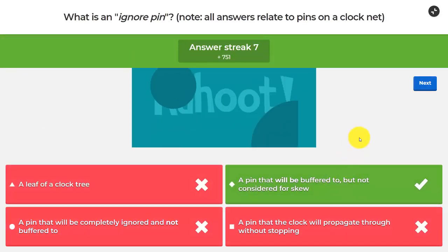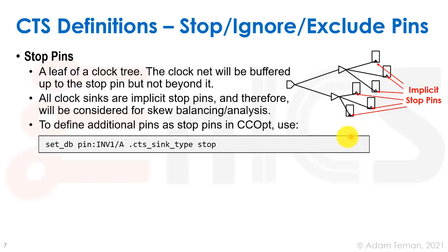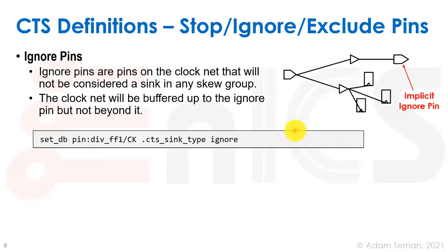Now, that's a pretty tough one, and probably what you should do is go into the documentation of your tool before you need to understand these things, because they are different between the tools, and there are little details here. But again, what we had here now was our clock source here, and the graph that goes down through the netlist and finds where the clock sinks are. But sometimes there's one of the pins here that really causes everything to have large skew and to cause lots of problems. For example, in this example I gave over here, we have an output. So from the clock source, we are going to the output, maybe to pass the clock signal to a different macro or something like that.